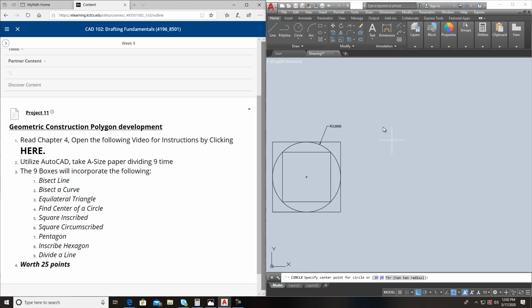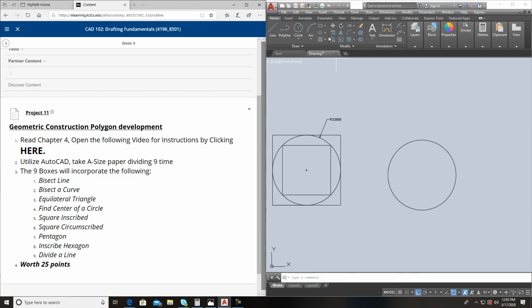I want to put another one over here, and I'll show you how AutoCAD does it if you're not familiar with it. You come up here, you've got rectangle or polygon, and I've got a 4-side polygon. In the center of it, it'll automatically catch that. And then if I do inscribed, enter, radius is 3. See how quick and easy that was?